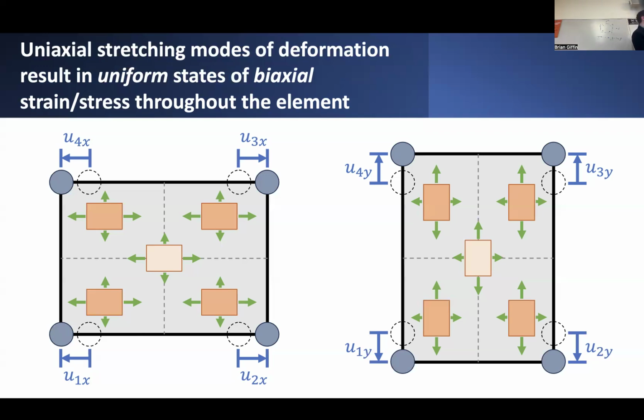Assuming that for the left would be negative and for the right would be positive. Well, it turns out that certainly position changes. The relative position of points is different, but it's important to remember what strain is. It's a measure of kind of relative displacement, right? And relative displacement is something like U2 minus U1. That would be the case in our one-dimensional problem.